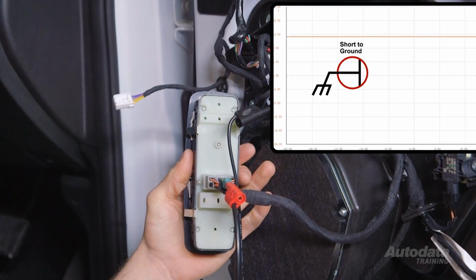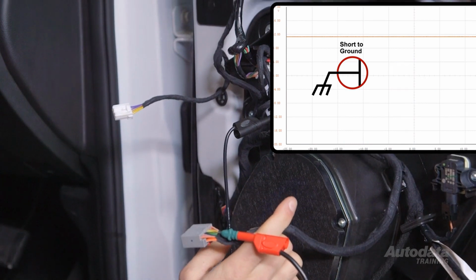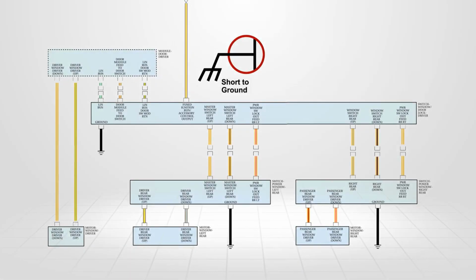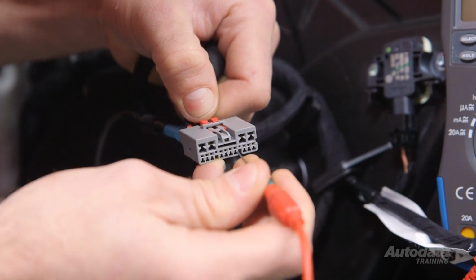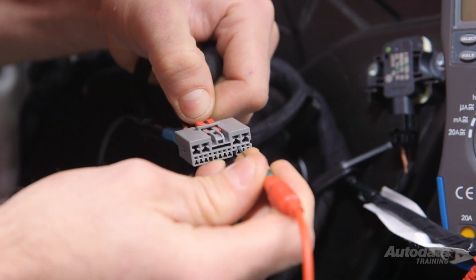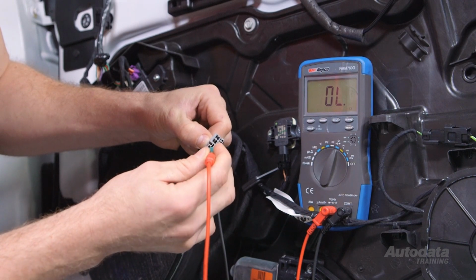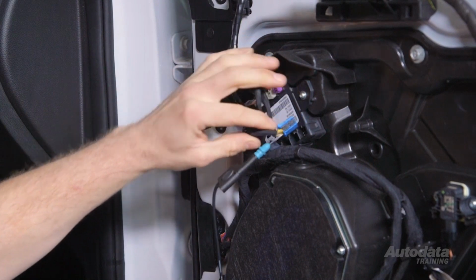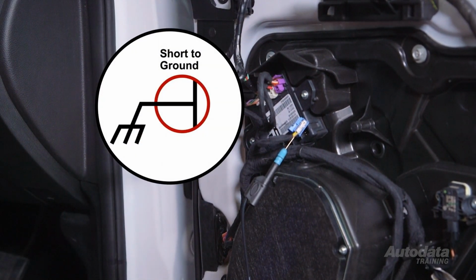To rule out the master or slave, disconnect these components one at a time while watching the trace. If the short disappeared after disconnecting either, then the fault has been localized to that particular component. Perform a continuity test between the LIN circuit and all other circuits in that connector. If continuity isn't seen, we've confirmed a module fault. If any voltage is seen after the components have been disconnected, then the short to ground is within the harness.